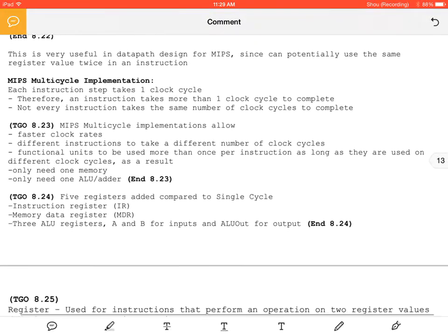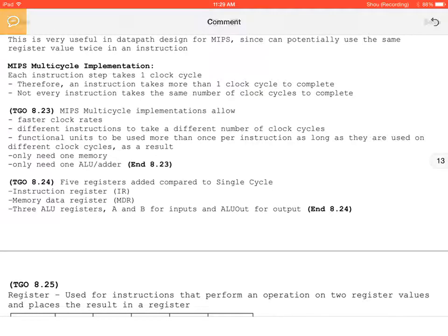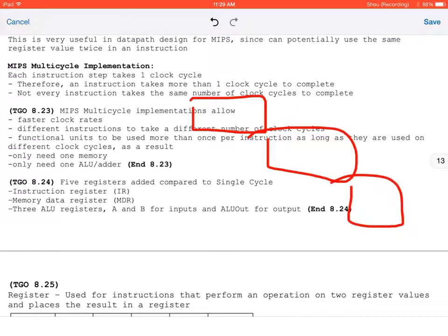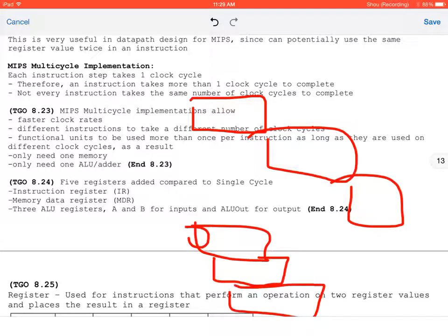All right, so MIPS multi-cycle implementation. For those of you who've done this before, basically the idea is single cycle, then you add 5 stages for timing, right? So pipelining, you have your 5 stages, but then it starts a new stage because there's a stage in between, right? But the reason why pipelining can be difficult to implement is because you have to worry about pipeline hazards, you have to worry about significant area overhead, you have to have a data hazard control unit, and you have to worry about propagating all of your control signals throughout the entire circuit through each register. So you have registers in between instruction fetch and instruction decode, execute, memory, and write back. And also you had to do all 5 stages.